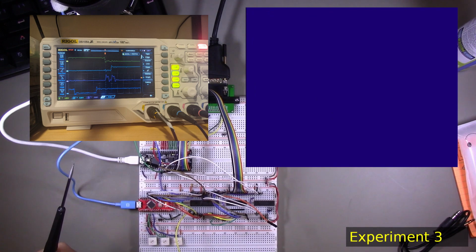And that, of course, meant that the loop that was trying to parse the received data bytes into commands and data couldn't properly distinguish the commands and the data. And that was why the consumer of those commands wasn't interpreting them correctly. So I fixed the Verilog module that implemented that 1 byte FIFO, and once I did that, everything started working.